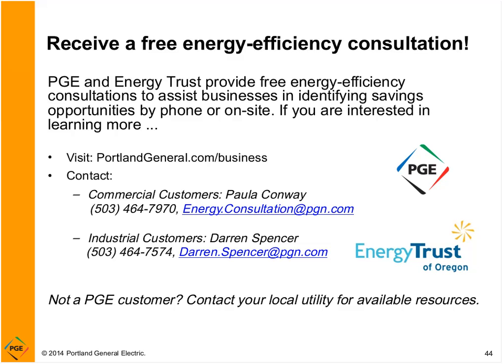What about outdoor lighting controls? Is there a way to replace standard pin timers to adjust for different day duration over the year? We mentioned briefly outdoor lighting controls. One of the most important things is not to have a day burner, not to have them on when the sun's out. So a photosensor is the thing that's most common to do that, but most people end up getting the cheapest photosensor they can, and they don't last very long. They might last for 5 years or so.